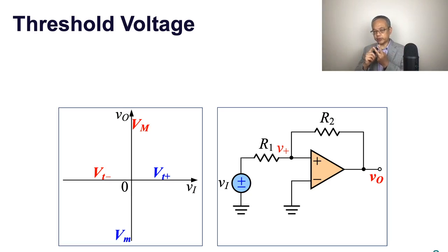So two important characteristics. The first one, positive feedback loop. The second characteristic, the input signal, the VI external input signal, is going into the non-inverting terminal of the op-amp instead of the inverting terminal, which you learned from the previous lecture, inverting bistable multivibrator. This is the non-inverting configuration. All right. So that's one of the major tasks of this lecture.